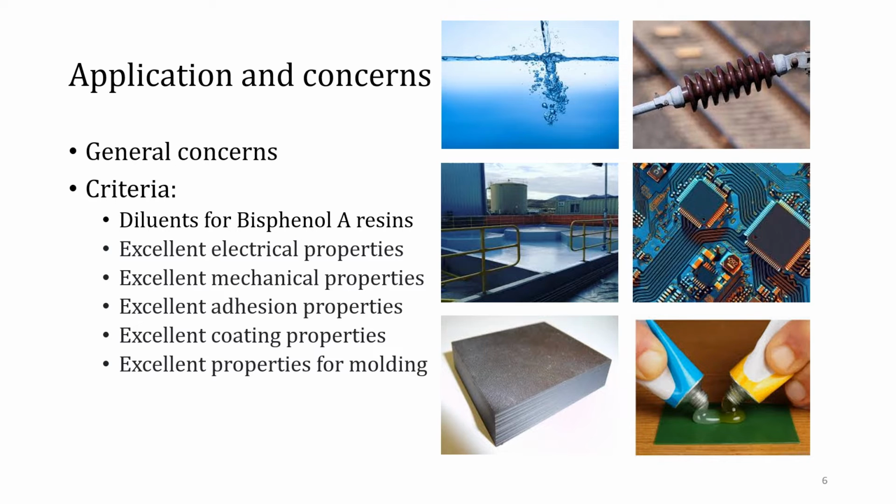Cycloaliphatic epoxies are not needed in flooring. None of the benefits or gains associated with cycloaliphatic epoxies are needed in floor epoxy paint, whereas it increases the cost by about 20%.